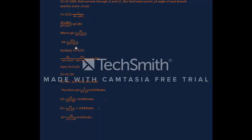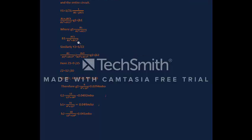Let's see. The real part is equal to R1 upon R1 square plus XC1 square. B1, which is susceptance, is equal to XC1 upon R1 square plus XC1 square. Similarly, we do this for the second question. And then it turns out to be R1 is equal to 9 ohm, XC1 is equal to 15 ohm, XC2 is equal to 10 ohm.